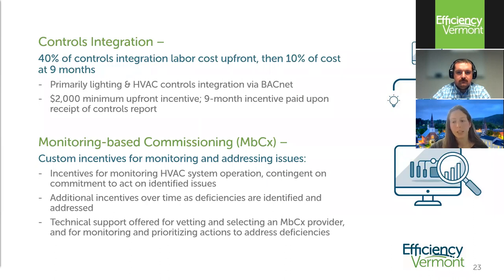Monitoring-based commissioning, or MBCX, is pretty advanced. It involves using regular pulses and trends of building management system data, as well as electric and fuel use data to identify and address issues in your HVAC system as they come up, and to find other opportunities for optimization.